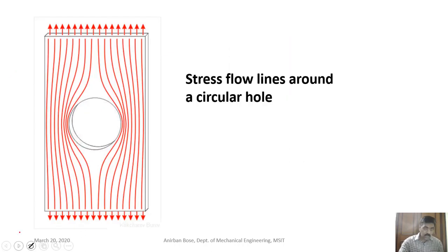So now here in this figure you can also see that there is a plate and it is axially loaded as shown in the figure, and there is a central hole like this. So the flow lines that will be continuous from one end to the other end will look like this. So it is very clear from this picture that the stress will be concentrated in these regions. So stress concentration will be very high. Okay, so this is what we actually mean by stress concentration.